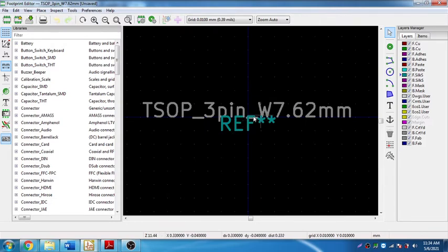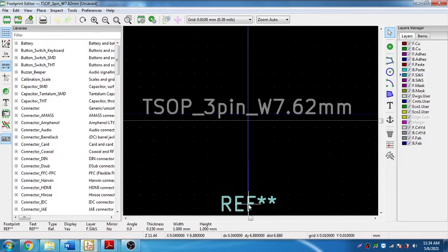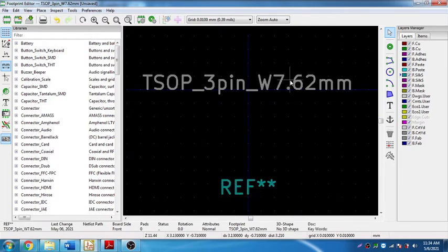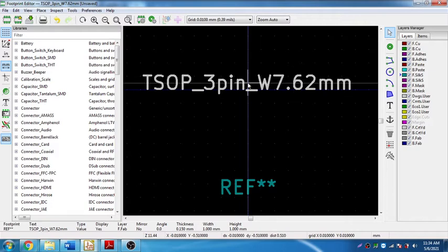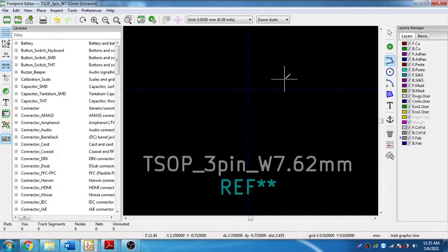Now let me start giving the reference for this. I will move this a bit down. So this also will move a bit down. So what I need is, I need to point the fab layer. Okay, just click on this fab layer here. I will take this 0 reference as a point. I'm going to make a rectangle first. I'm going to draw a rectangle. So take this add line and start from the 0.